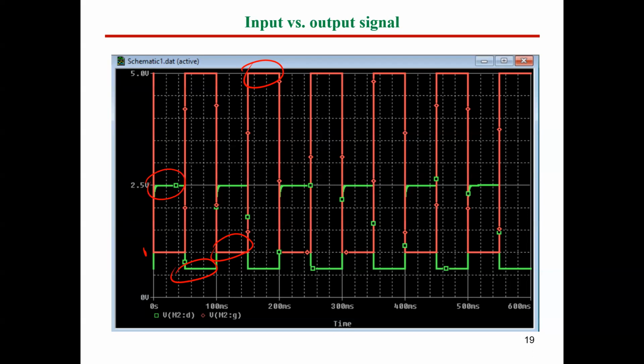And the active low signal, it's better to be very close to ground or 0. So I do recommend if you test or make any driver for any transistor, you apply the active low signal as 0 volt instead of 1 volt like that. But here we just would like to investigate one case. So this is now, guys, called transient analysis.